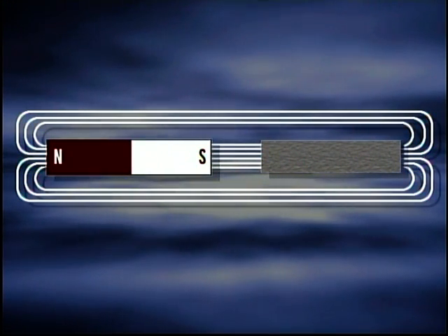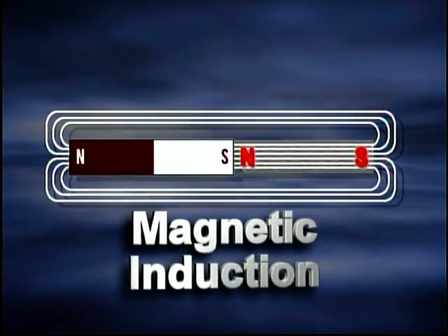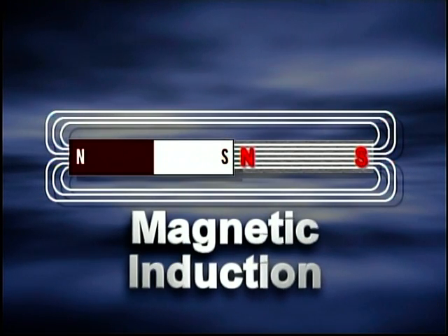Now, let's see why magnets attract objects made of magnetic or highly permeable materials. Since such magnetic materials provide an easier path than air for the magnetic lines of force, some of them are diverted to the magnetic object, causing the field to be distorted. Remember that lines of force tend to contract. Therefore, as they pass through the magnetic object, they pull it toward the magnet. The lines of force passing through the magnetic material have made it into another magnet. This process of being magnetized is known as magnetic induction.